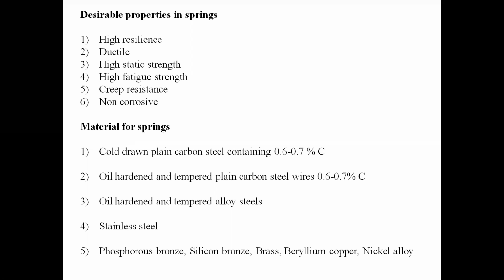It should have ductility. The material should be ductile so it can be drawn into wires. It should have high static strength so that whatever load is there, it can be sustained by the spring. It should have high fatigue strength. Why is fatigue strength important? Because the spring is generally subjected to repeated loading. Because of the repeated loading, the spring gets fatigue, so it should have high fatigue strength.